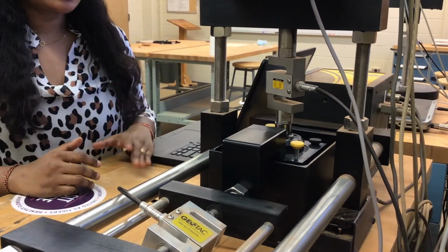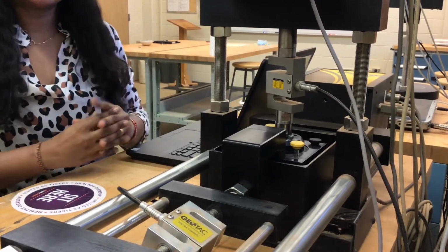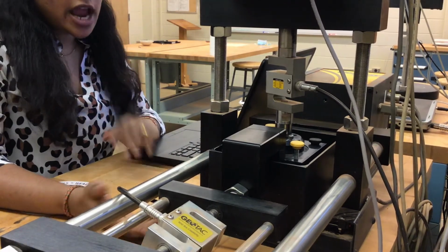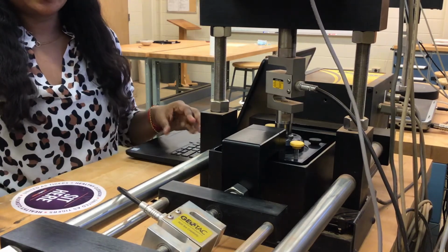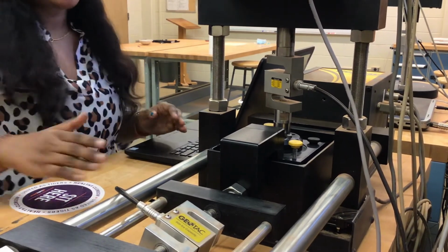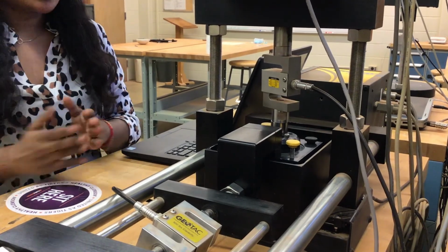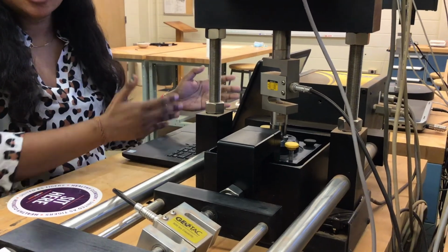So what happens in running a shear test? First, the load will be applied and a consolidation will take place for this soil. But as we are using sand and it is drained, the consolidation will be very fast. That will be within very few minutes, not like clay. So after the consolidation part is done, the soil will start to shear. So at the end of the test, we will be getting all the deformations and the stresses from the computer.